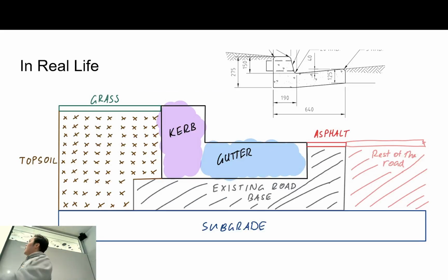Okay, so if you see along your road, you have the curb that is sticking up, and then you also have a little bit of concrete on the side. That's called a curb and gutter. So the curb is the part that sticks vertical, and the gutter is the side that is on the flat part next to the asphalt. So this is actually what it looks like. This is a cross section of what the road looks like when you look at a curb and gutter, right? So you might have some grass, some turfing on the side, and you have some soil underneath. And then you have your curb and gutter that is flush with it, and then you have your road outside.